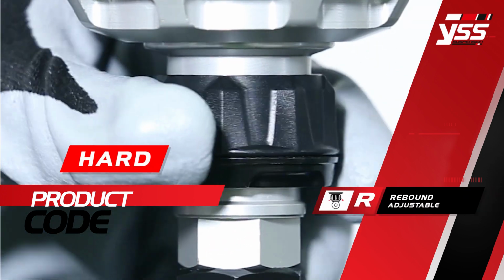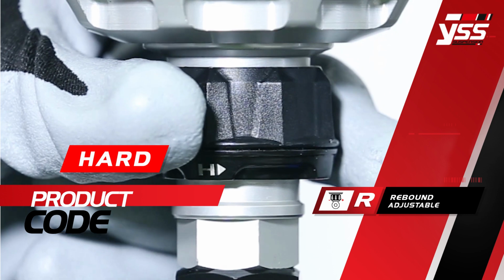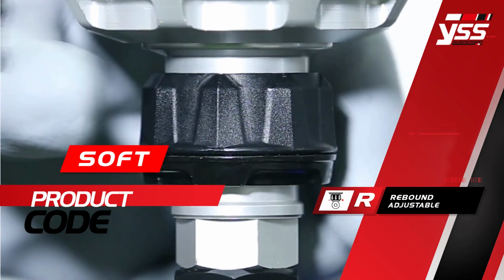R: Rebound adjustable, to support and control spring and shock absorber movement as desired. Adjust the knob to control the flow of hydraulic oil through free bleed. Rebound knob is designed to have a click sound when adjusted.